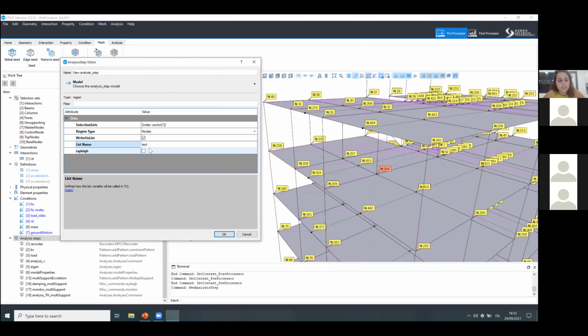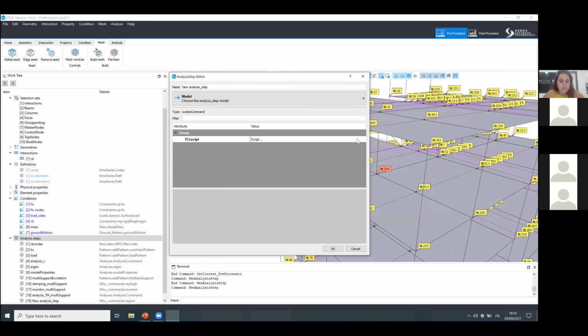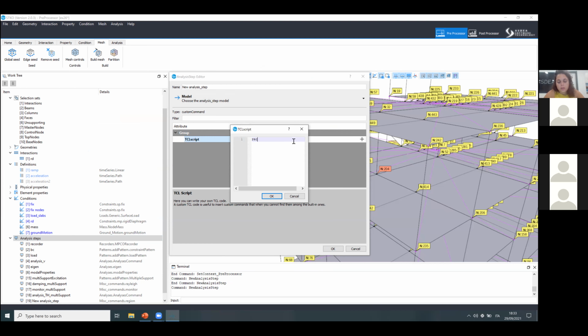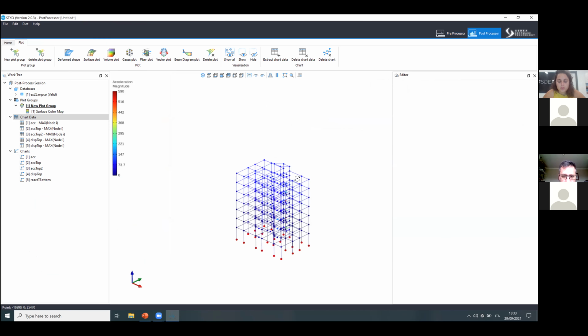And this value here is like creating a variable in your, let's say, STKO environment. And with this variable in a custom command, you can actually extract the value with a normal recorder, as you would do in an OpenSees script. So you go here, you go to recorder, and you can just write the ID of the elements, etc. Like you would do in a normal STKO script, and it will be done not by the MCU recorder, but the OpenSees recorder.